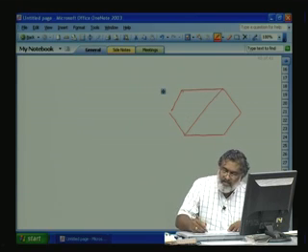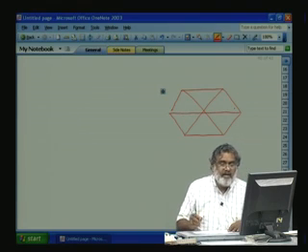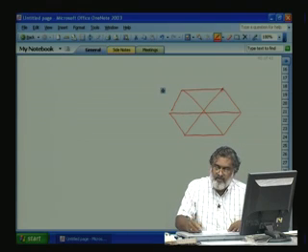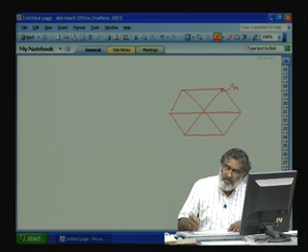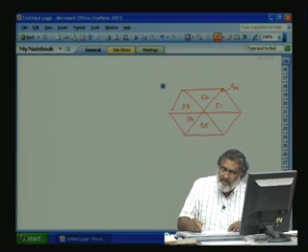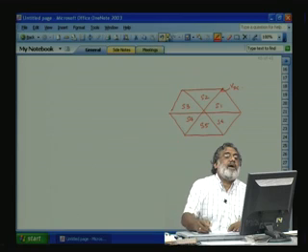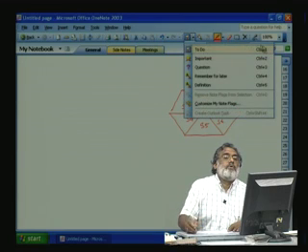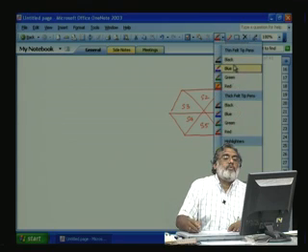It is a hexagon with equal radii. Radii means amplitude of the hexagon. This is equal to Vdc, depending on the DC link voltage. So, this is sector 1, this is sector 2, sector 3, sector 4, sector 5, sector 6. Now, from sector 1, our alpha has moved to sector 2, let us say.